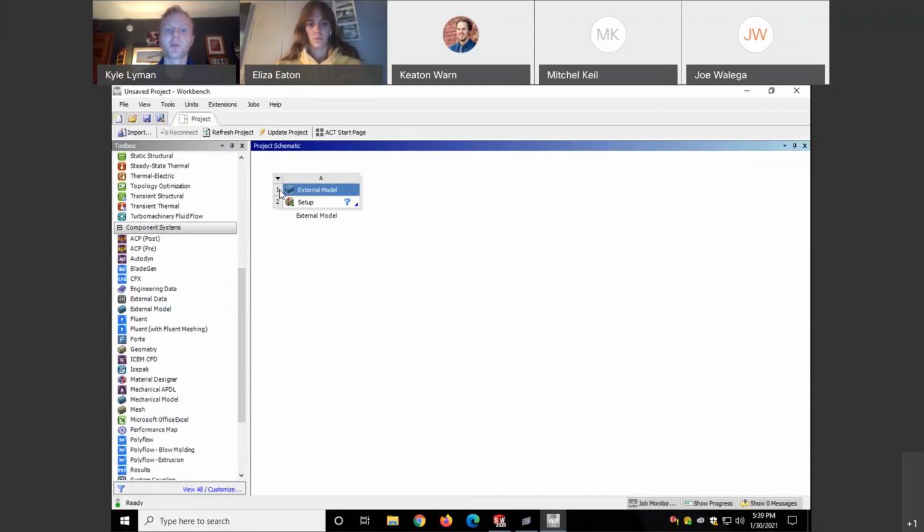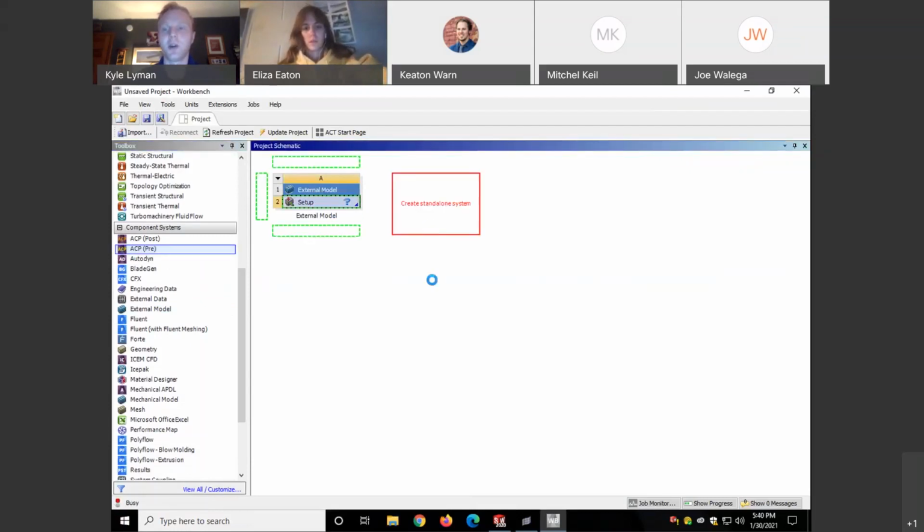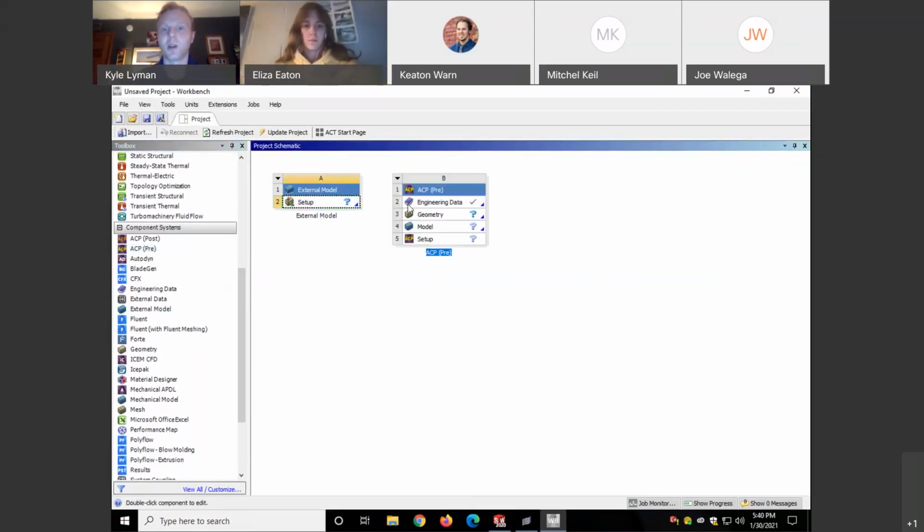This first one, number one, is always just the label of the module that you're using. Number two is the next step in order of what you want to do. So you can see with any system that I create, it'll always sequentially number what I'm going to want to use. In this case, I've gone ahead and selected ACP Pre as well as External Model because I will be using both of these in this tutorial.